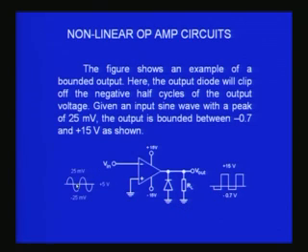And when the voltage Vin goes less positive, that is, going negative on this side, you would find the plus will become more, and therefore it will go to plus VCC. For plus VCC, this diode is reverse biased, and therefore plus VCC will come out as such. So by using this diode, I have cut the voltage on the negative swing. It is only minus 0.7 to plus 15, almost like 0 to plus 15, and therefore this can perhaps be used in different circuits for digital applications and things like that.